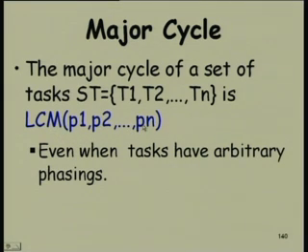Normally we will see some situations where we need to store a slightly larger schedule if we have not designed our cyclic scheduler properly, but this is the one we can do best. We cannot reduce the major cycle below LCM of P1, P2, Pn, isn't it? So here also we will have to set at least one timer for the major cycle.